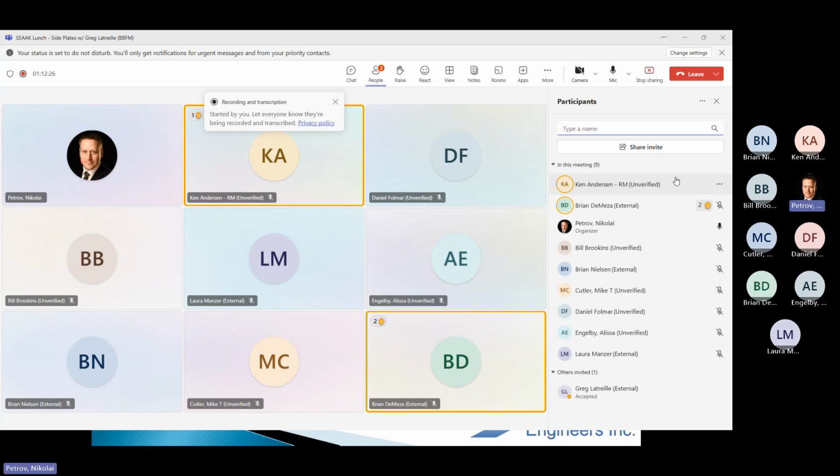The biggest thing that you find up here is moment frames with non-qualified connections. There are several medical office buildings and clinics that have HSS columns with a sort of stop sign plate above and below the beam that welds all around it. It makes this sort of 4-way moment frame. Not at all allowed under the current code, but they did it in every bay.